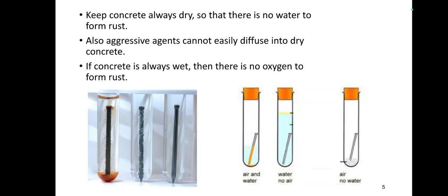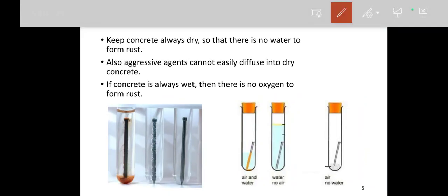As you already saw in the mechanism video, corrosion happens in the presence of water and air, because the cathodic reaction needs both components, water and air, to start. Take an experiment which demonstrates when corrosion will happen. You can see a nail placed in a test tube, and they are conducting three different conditions. One is filled with air only, meaning there is no humidity or moisture. If you keep it like this, corrosion won't happen.